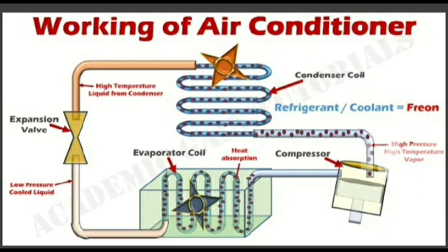After passing through the compressor, it flows through the condenser coils. A big, often loud condenser fan helps to push air over the condenser coils to facilitate heat transfer outdoors. Refrigerant then cycles back over an expansion valve, depressurizing it and cooling it down. It then performs the same heat absorption process over and over again.